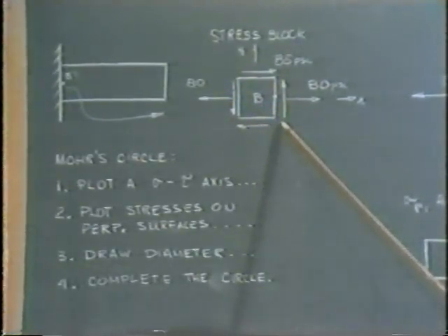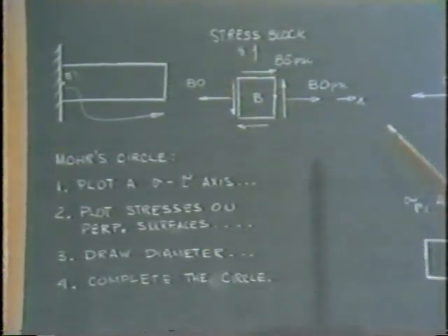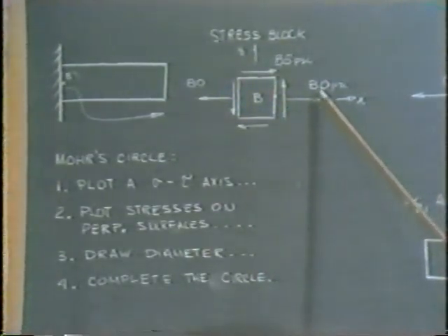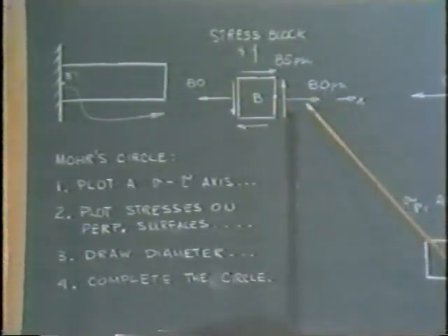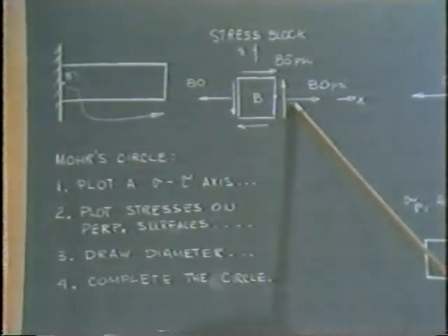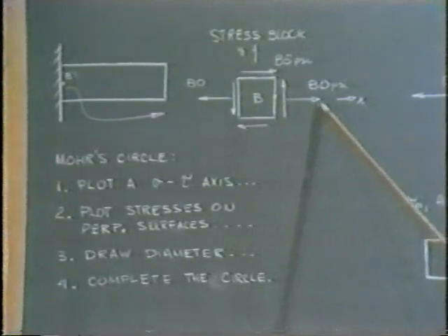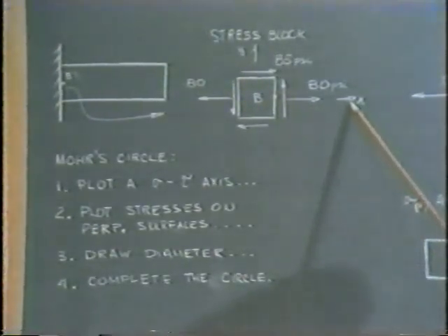On a vertical surface here that would be cut if I were to expose a cross-sectional area are the stresses that point B would experience. Recall, for example, the normal stress of 80 psi would be in tension, and I've identified that perhaps as an x-axis since it's parallel to the x-axis in our beam.